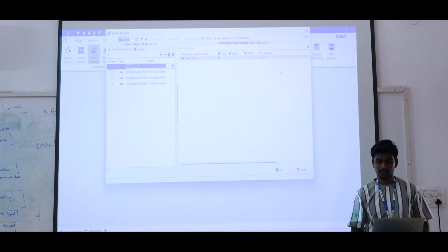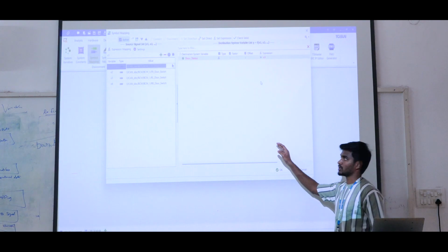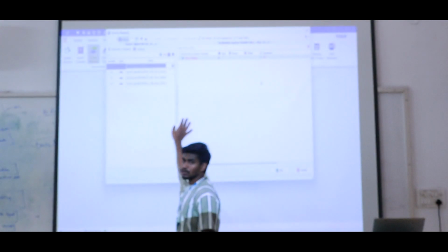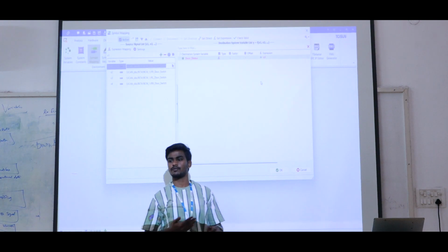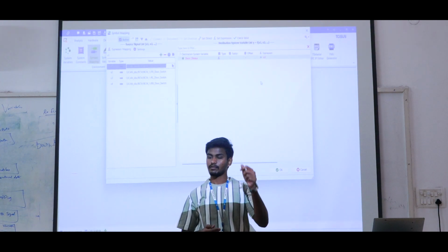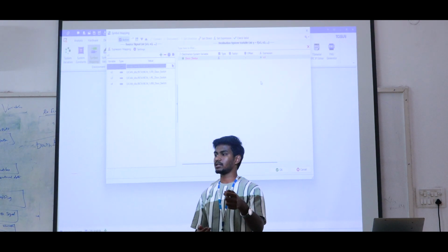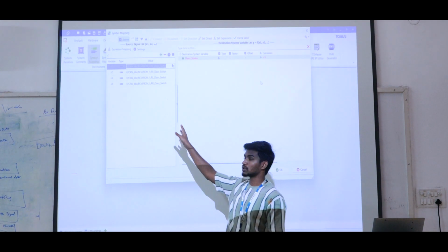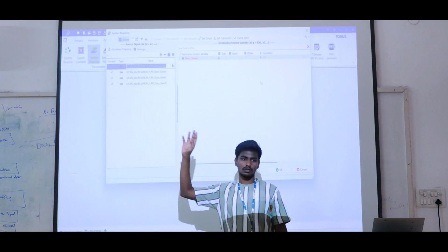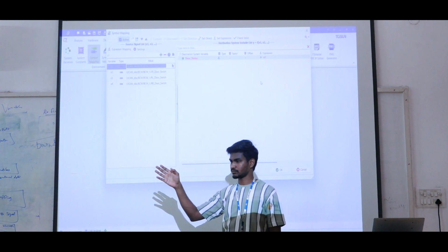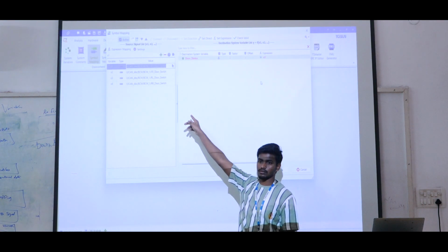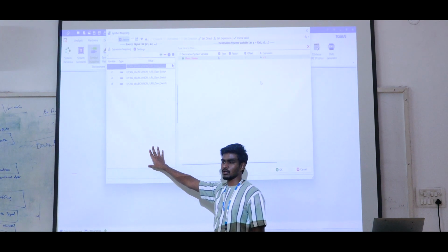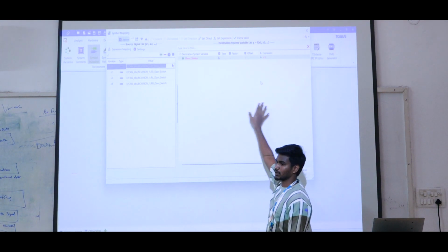So the next step is why I am adding these 4 expressions. Now we are going to check the common status, which is door status. So now we can take the real-time example of RKE, remote keyless entry. Whenever we are pressing the lock button, it is checking 4 doors. So when it is working, it checks whether the 4 doors are closed or not. So 4 doors closed means we are using an AND gate. So door value 1, next door value 1. So if all the door values are 1, the final output means the doors are locked. So using the logic operator here.